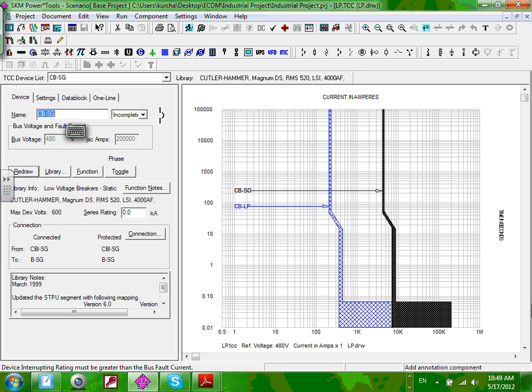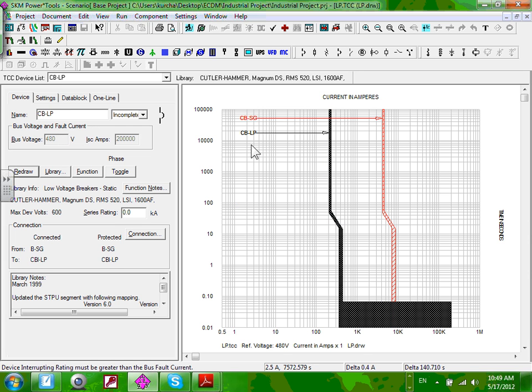Perfect. Can you guys see the main circuit breaker right here, and the panel circuit breaker? Remember when we were talking about coordination, if these two curves are touching each other, they are not coordinated. Are they touching each other anywhere? How about the bottom here? How do we explain the bottom? Yeah, the bottom is instantaneous. That's where all hell breaks loose.